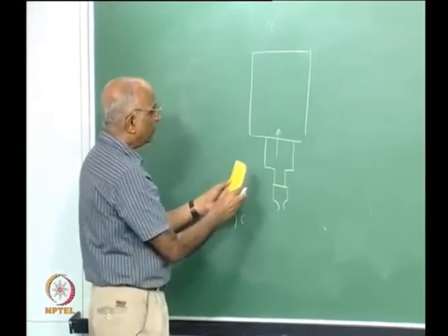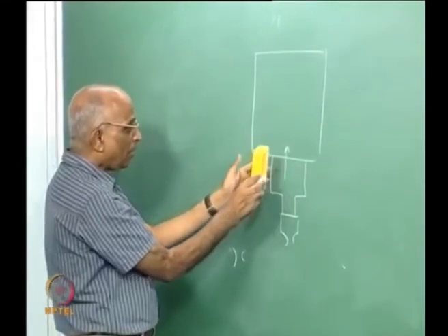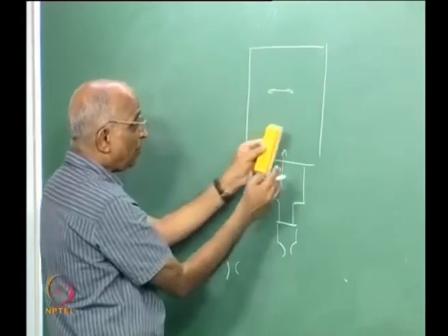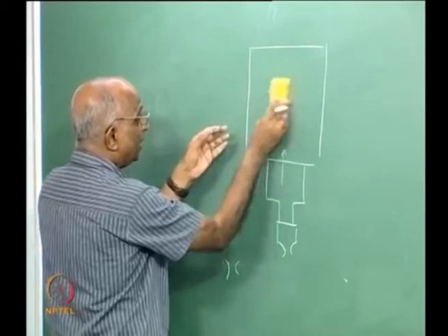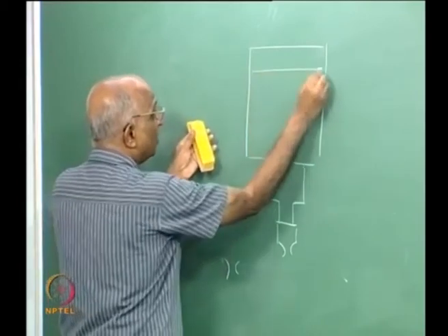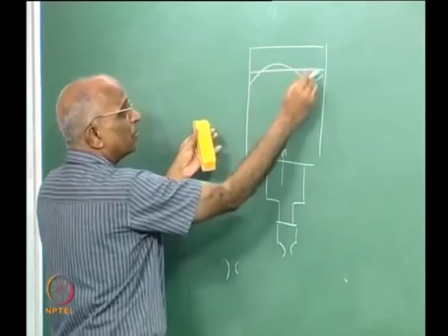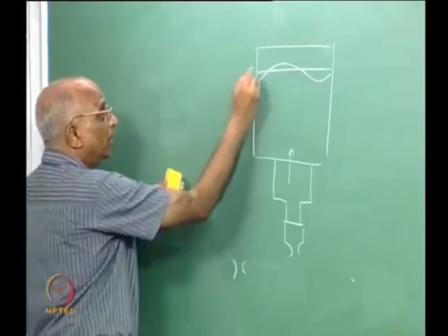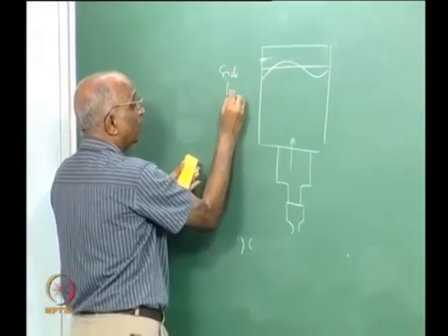Now, if the rocket is going up, I just get a straight axial load, but the rocket also turns and so on. That means I could get side loads, not only from the rocket, maybe from the wind bias. And when I get the side loads, the surface of the liquid, instead of being plane, becomes a wave motion. And this wave motion, traveling up and down, again provides side loads to my rocket.